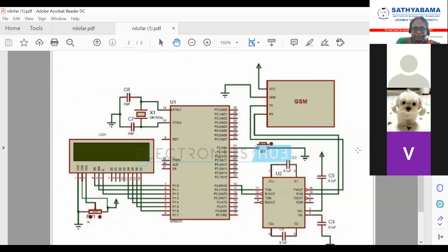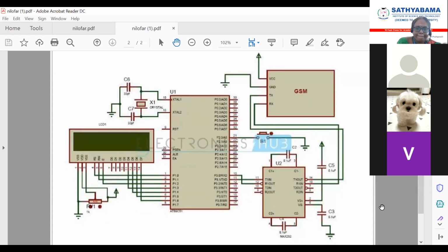The LCD module connects to port 2 of the microcontroller. Data bits D4 to D7 of the LCD are connected to port 2. The LCD is used here to display received messages. A button connected to port B of the microcontroller is used for sending messages. Applications include automobile accident detection, robot control, GSM based telemedicine systems, and ATM theft precaution systems.